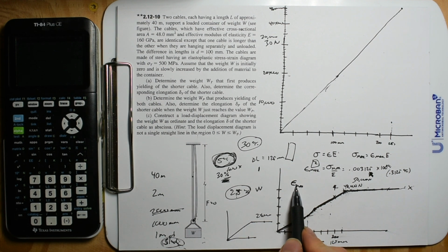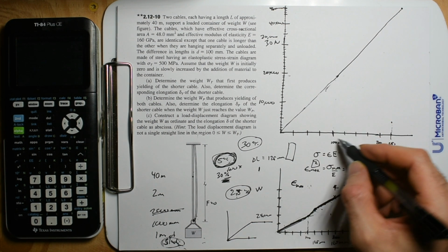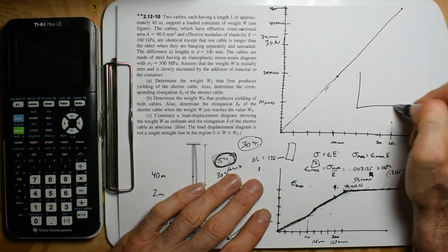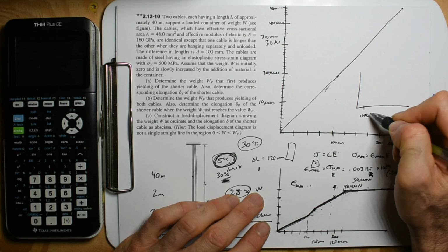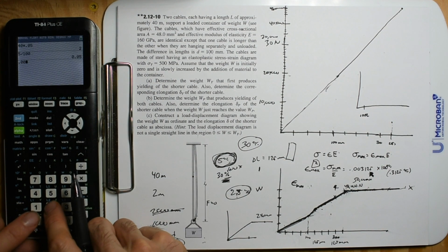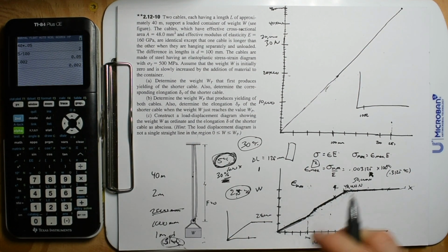But yeah, that's the take-home message: when you're working up to that max strain, or change in length per length, well, that's every material. That's just a tiny amount. You know what I mean? Let's do it for steel. Steel would be 0.002.